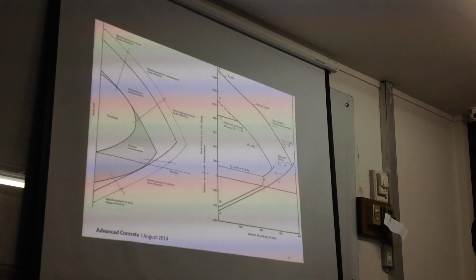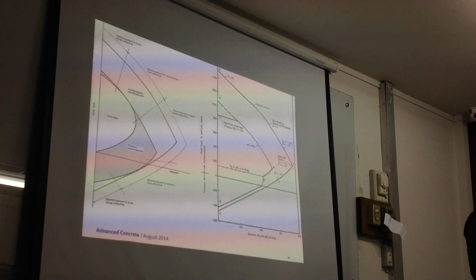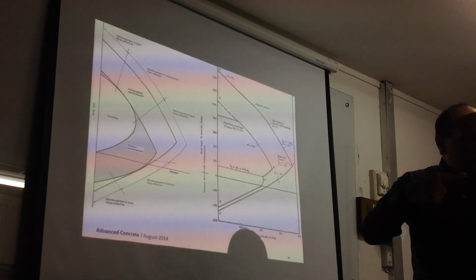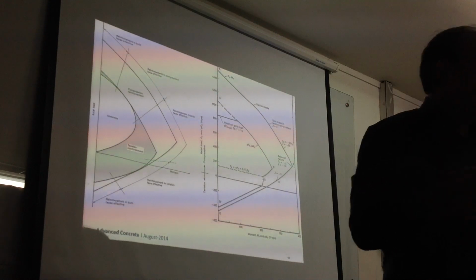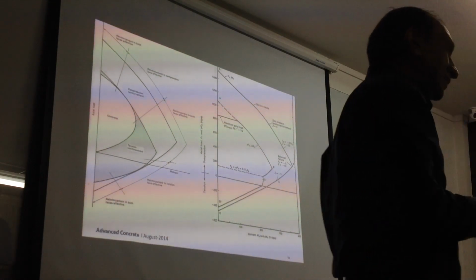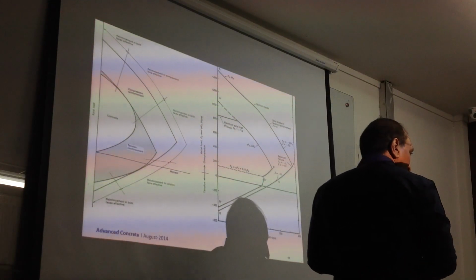So we need to know whether the bar will become in tension or will not come in tension. If it comes in tension, tension splice rules will apply. If it remains in compression, compression splice rules will apply. And the tension splice rule means a longer splice, more reinforcement is needed. Right? So you need to know these things.